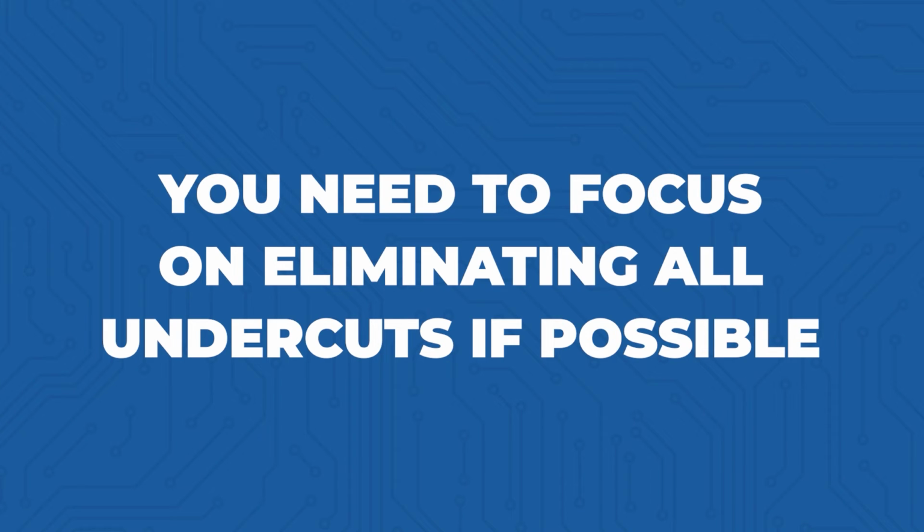Just keep in mind, side actions are going to drastically increase the cost. It's going to lower the reliability of the mold because now you've added moving parts, and that just adds a lot of extra complications. Just be sure when you're designing your 3D model that you or the 3D modeling designer has a solid understanding of injection molding.